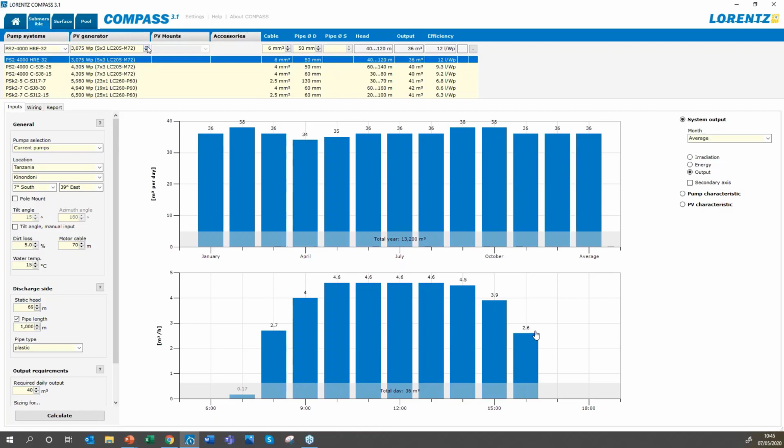So I hope that makes a lot of sense. You're giving the customer here 2 options. Here's a solution which gives you the water you require today. If you think there's a high probability that your neighborhood community might want to join you in 12 to 18 months, as you mentioned, you could choose this pump now, but we'll install less PV on it, so less solar modules on, and then you can just add solar modules when the next community comes on. So this is a really good way of budgeting.